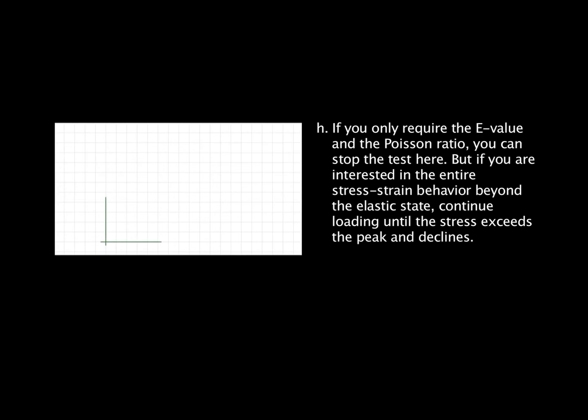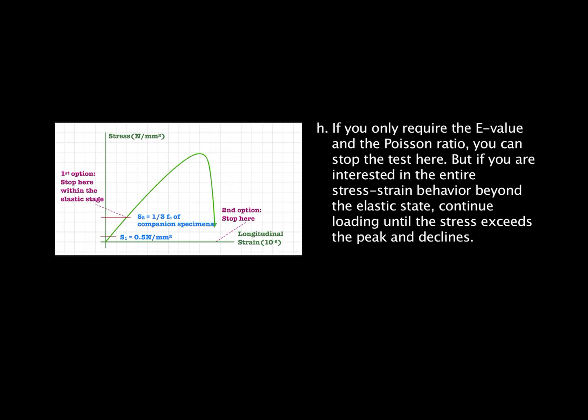H. If you only require the E value and the Poisson ratio, beyond the elastic state, continue loading until the stress exceeds the peak and declines.